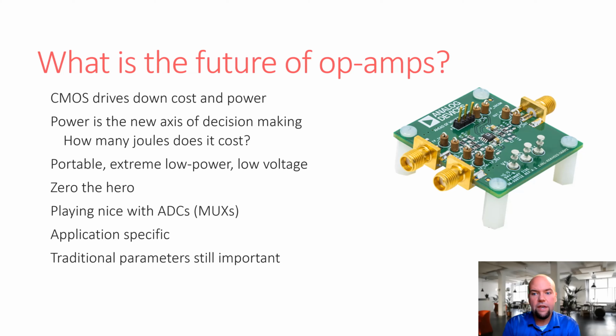And there's a whole family of these. They do all sorts of crazy exotic things to cancel out little drifts and little offsets and little errors in these sorts of devices. And they can be very expensive, but this is one category of the future of op-amps: playing nice with things near zero, of amplifying zeros. Also playing nice with ADCs.